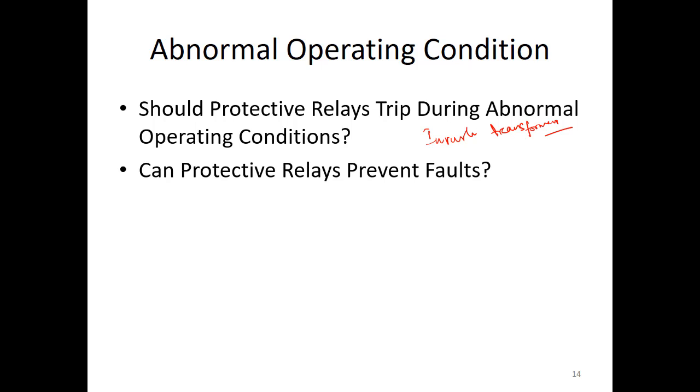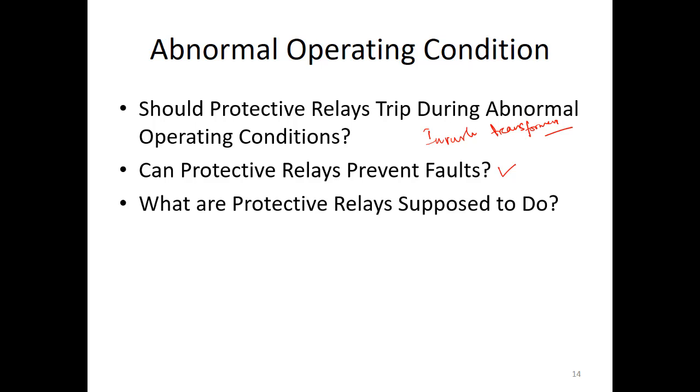So another question is, can protective relays prevent faults? Obviously protective relays cannot prevent a fault, but we can protect the system from the fault condition. As soon as the fault is isolated, it is better for the system and the system can revive very quickly. So protective relays cannot prevent faults, but they can protect the system, protect the elements of the power system, right?